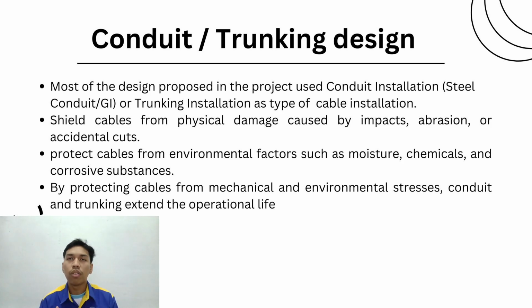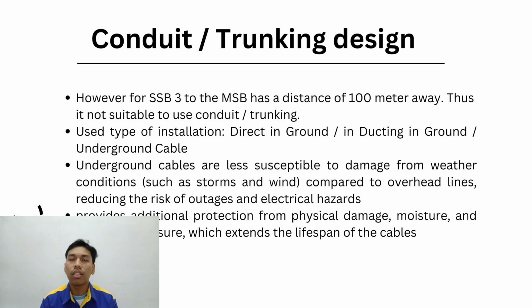However, for our design, for SSB3 to MSB, which is SSB from mosque to MSB, it has a distance of 100 meters away. Thus, we consider it not suitable to use conduit or trunking installation type. So we use another installation type, which is direct in the ground, in ducting ground, or underground cable.